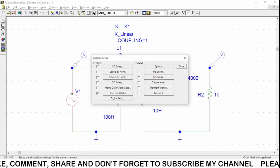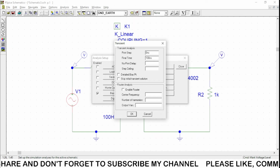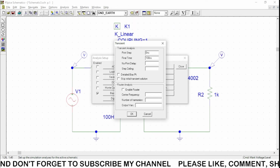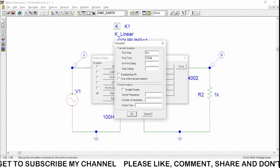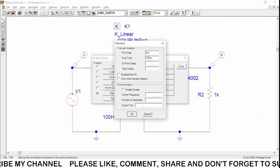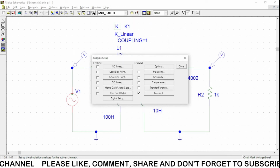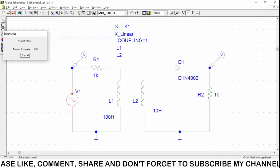So now in this case, we are going for the transient setup as we are going to vary the voltage or actually the frequency. So we have to see between 0 to 100 milliseconds. Okay, I'm unchecking the bias point. Okay, close, analysis, simulate.